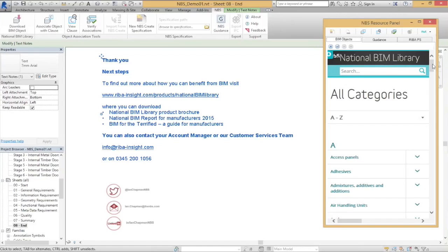That's a good question, because there's lots of products out there. They're defined as a layered object, and essentially a layered object is defined in 2 dimensions. So it may have a thickness, it may have a build-up, there may be a number of components that make up that build-up, but they're defined essentially in 2 dimensions. So there might be an outer skin, which might be 10 millimeters, there might be an inner skin, and a further outer skin, which essentially creates a sandwich, creates a layer. You can have many layers in a layered object, or you can just have a single layer.